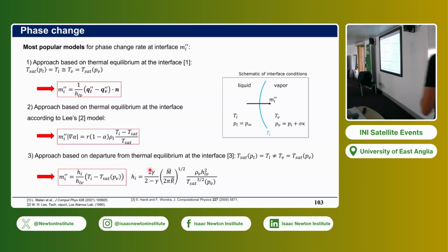Now, how do we set gamma? For the analytical test cases, I typically use gamma equal to 1. So in the absence of any specific information, I use gamma equal to 1, and this gives the best agreement with benchmarks. If I have experimental data, I can try to get a bit of a more accurate value of gamma.